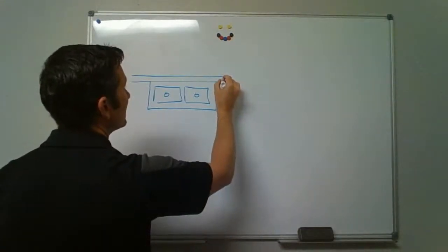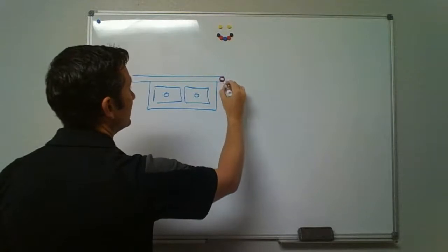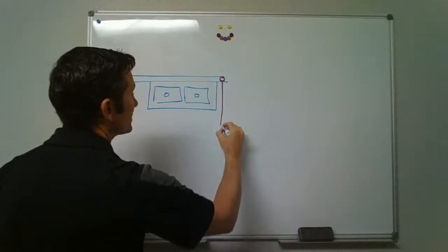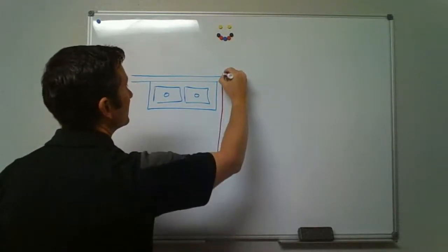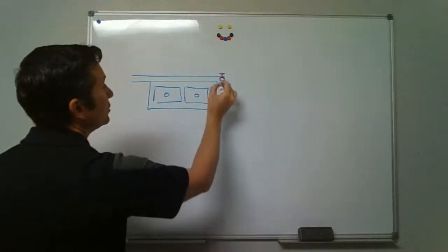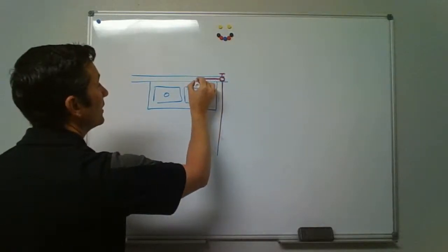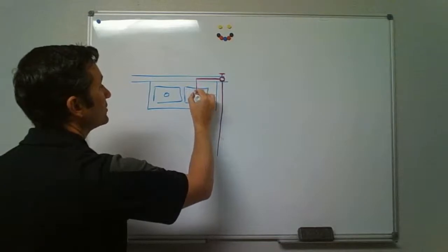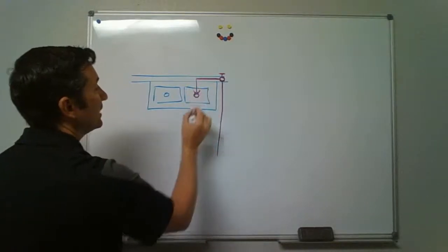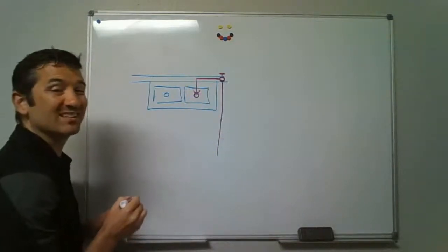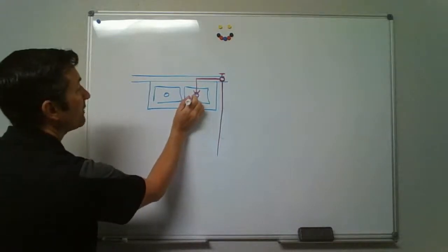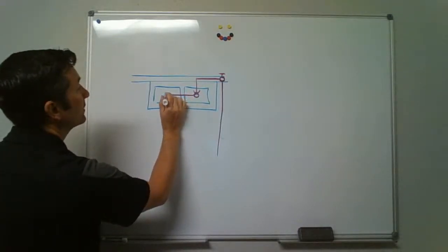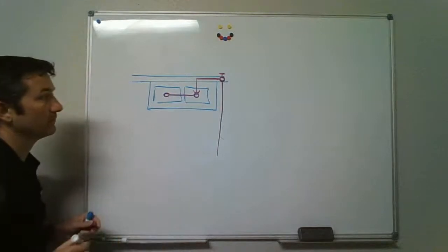But now let's put the vent over here. Drain goes out in this direction. Clean out in the back. You're going to arm over out of the wall, symbol for the P-trap. And then to connect the continuous waste, you're going to come off of this line over and turn vertical again. Okay?